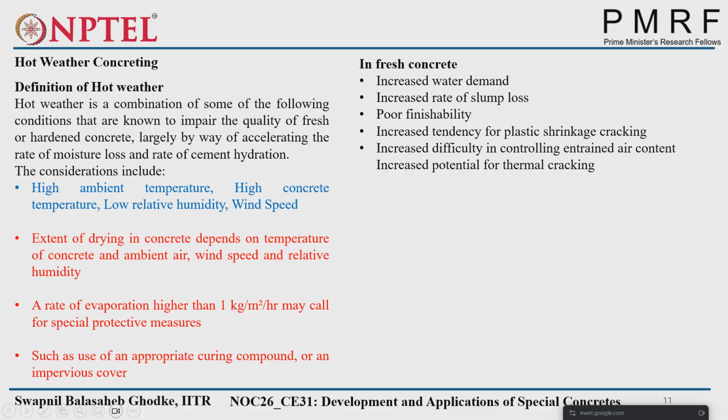There is an increased tendency for plastic shrinkage cracking, because in the plastic state of the concrete there is high evaporation of water in hot weather conditions. That's why we get a higher amount of plastic shrinkage cracking in normal concrete. If you have seen, when any type of rigid pavement is constructed in the summer season, there is a very high chance of cracking on the surface. That's why we always keep water ponding continuously on that surface, and some gunny bags are placed on that surface. And